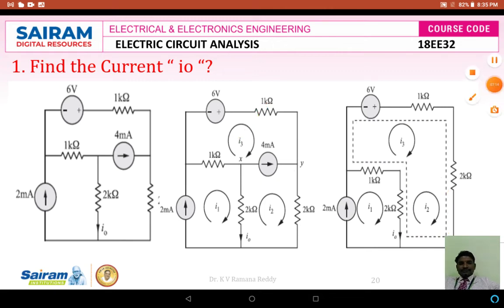Now for the given problem there is one more direct inspection method we have to apply, and we can identify that easily. In loop 1 there is a current source of 2 milliamperes. It is a self current source for loop 1. So I1 current is equal to 2 milliamperes. From the direct inspection method we can identify that answer.